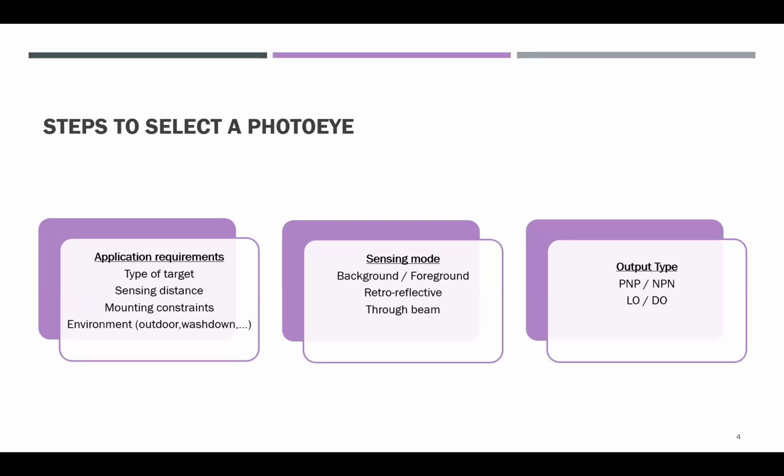And these three are the most important, but of course there are other things like what connector type is preferred, flying leads or male connector, and what about mounting, in terms of whether we need nose mount or side mount and things like that. There are many more factors. If we consider that, we can narrow down the exact sensor family, but these three areas are the most important.